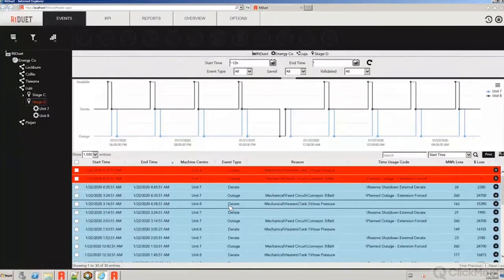If I could just chime in. What we actually track is the megawatt availability we're declaring to the market. And if the megawatt availability comes off the registered rated value, RtDUET will say, has it gone to zero? If it has gone to zero, it registers and starts an outage event. And if it goes to something above zero, but below the registered megawatt capability, it starts a D-rate event. And that's very similar to what happens in the North American markets.